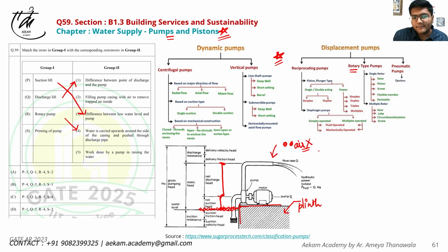So what do they generally do? If you have seen, even in your society or your house complex, your watchman or maintenance operator in the morning puts some water into the pump, from a Bisleri bottle, such that the entrapped air gets out. So this is exactly what priming of pump is, which is filling pump casing with water to remove entrapped air. So this is a very common example which we see in our day-to-day life.